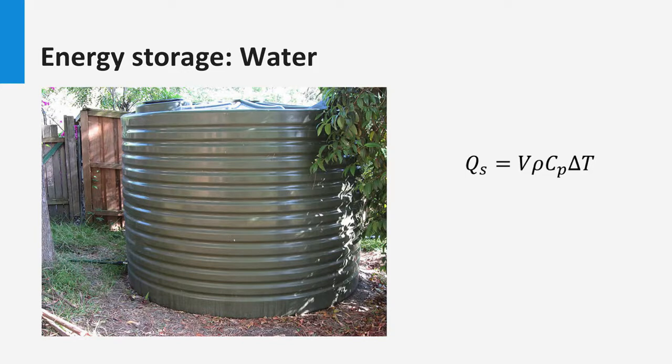The temperature range for operation is limited at the lower extreme for most applications by the requirements of the process. The upper limit may be determined by the process, the vapor pressure of the liquid, or the heat loss. The heat loss of the tank, Q loss, can be determined by the following expression, where A is the outside area of the tank and U is the global heat exchange coefficient. The value of U gives the quality of the insulation and usually varies between 2 and 10 watts per Kelvin. This U is also a function of the different media between which the heat exchange takes place.